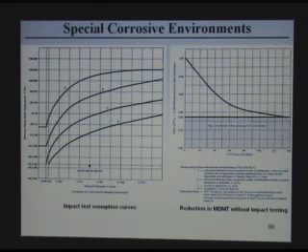So if you have a thickness, say a 3 inch thick component, and your design temperature is -20, and you're here, so you have to impact test your material, make sure this material is tough enough, otherwise you have to use some other alloys.